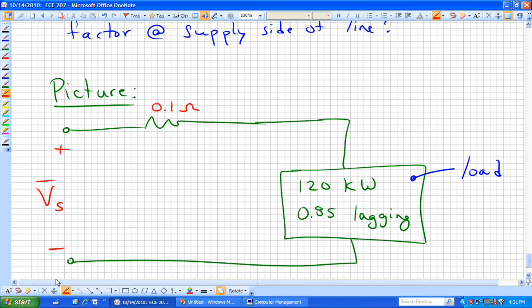The question was, do we have to worry about it going and coming being incorporated into the distance? No. Let's just view that as one length, which is a mile, and that 1 mile of cable has an impedance or a resistance of 0.1 ohm. And we're going to lump that into our circuit here of our supply side and our load side as just a discrete resistor of 0.1 ohm.